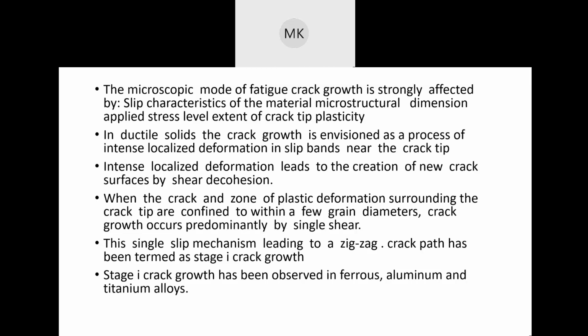So when the plastic tip or the crack tip and the crack size is a few grain diameters in size, at that point, that whole crack would become cracked due to that single shear that is happening in that single plane. And this single slip mechanism leading to a zigzag crack path has been termed as the stage one crack growth.